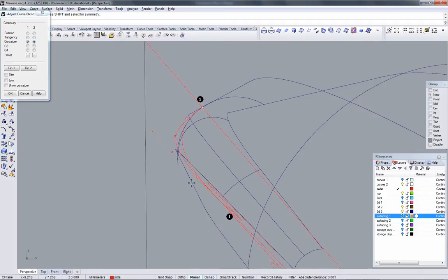So I'm going to push it up from the back a little bit. Pull down the outer handle. The way these handles work, this is the tangency to the base, and this is extending out. So heavy control from here, delicate control from here. If I really want to make a substantial push, I do it from the base curve. And if I want to make subtle changes, I do it from the outer point.